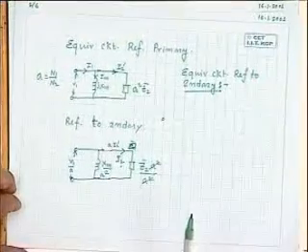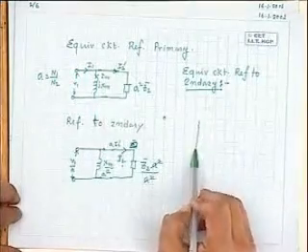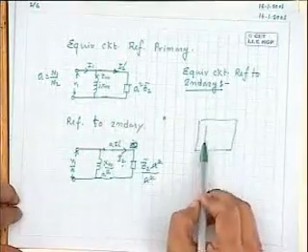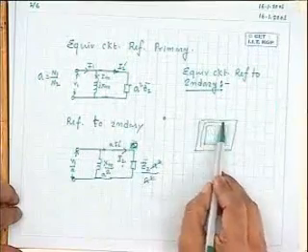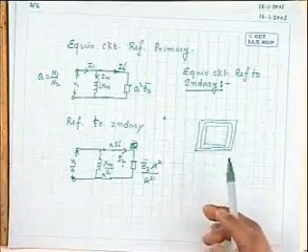If the flux is constant, sir, how can the MMF be constant, sir? Because the reluctance will be different. How is reluctance different? The number of turns will be different. The magnetic circuit, the path through which the flux flows, that reluctance is constant. I am not changing the magnetic circuit. Am I changing? What is the expression of the reluctance that I have done in the first class? It depends upon the mu of this material, cross-sectional area of the core, length of the magnetic path, etc. That you kindly go through it.